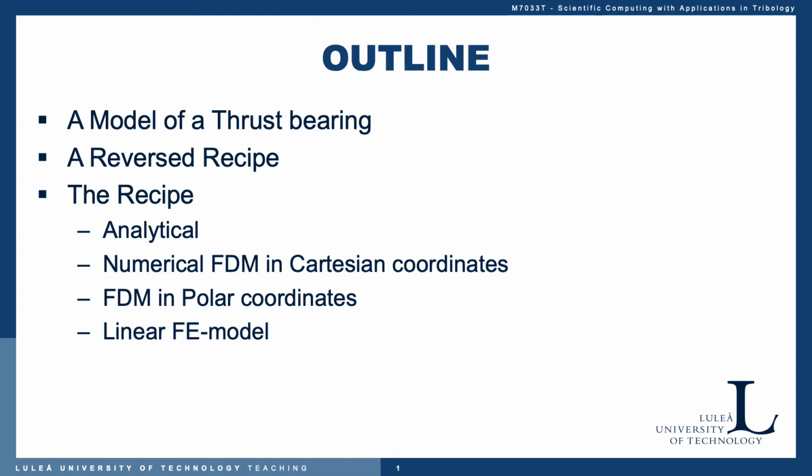The outline of this video is to first introduce you to a model of a thrust bearing where we couple some physics, and then an overview over what I will call a reversed recipe, and then we will reverse that to the original recipe, which will start off with analytical solution of the corresponding linearized simplified problem, and then successively more and more complexity is added in numerical finite difference method based solutions in Cartesian coordinates and then in polar coordinates, and then we obtain a linear finite element model which we can implement in, for example, COMSOL Multiphysics.